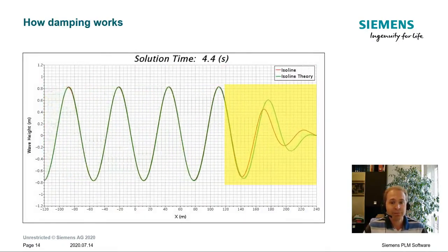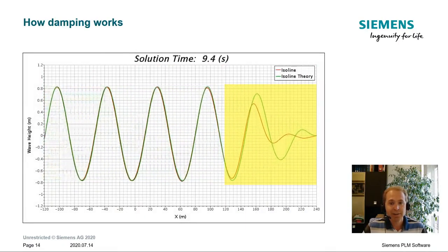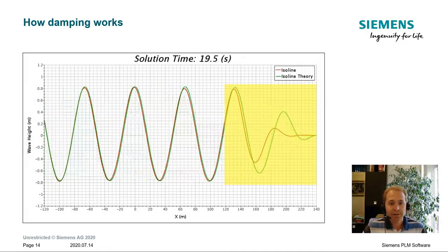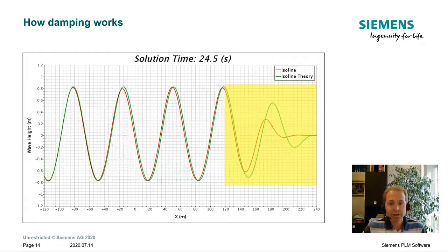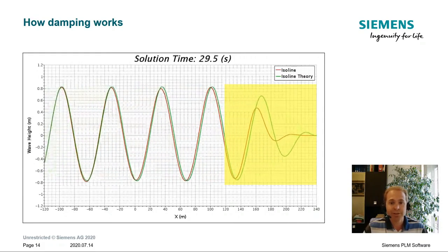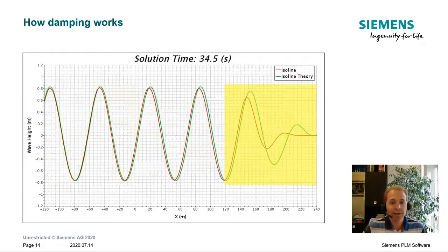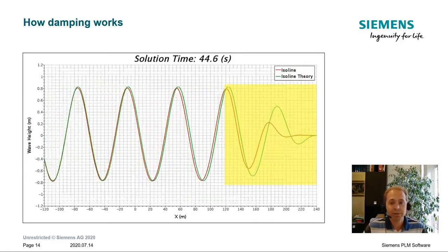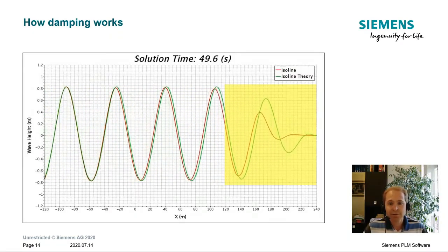The first approach, the most classical one, is that of the damping. So attached to the outlet, we define a region in which we apply some forcing terms to flatten out the wave and impose a flat wave boundary condition. As you can see, this works pretty well.